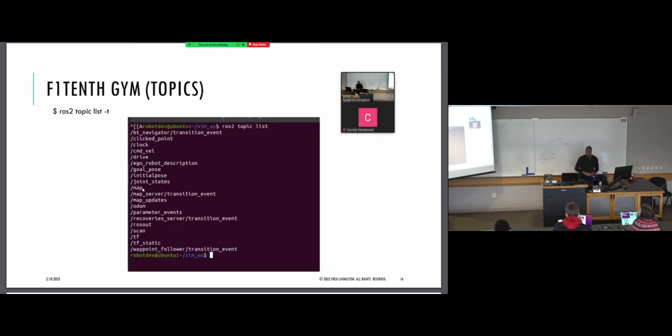That map is just the drawing of this map here. The odometry is the orientation and position of where the robot is from the starting position. I started here and moved the robot forward. Everything is usually in meters. So I moved it from here to here. It's using the velocity from the IMU and integrating the velocity to get the position.